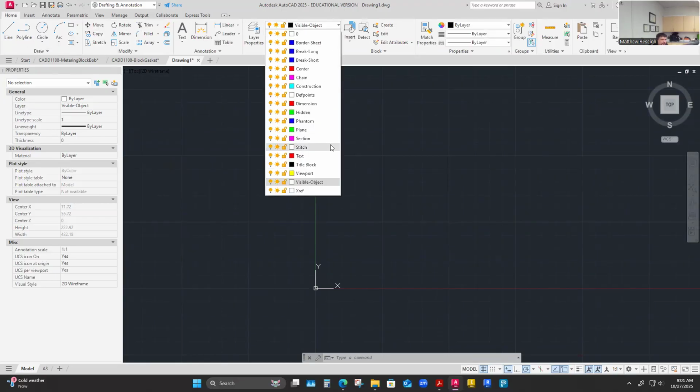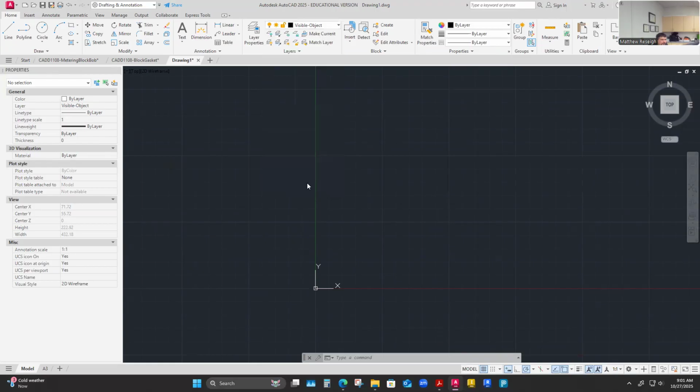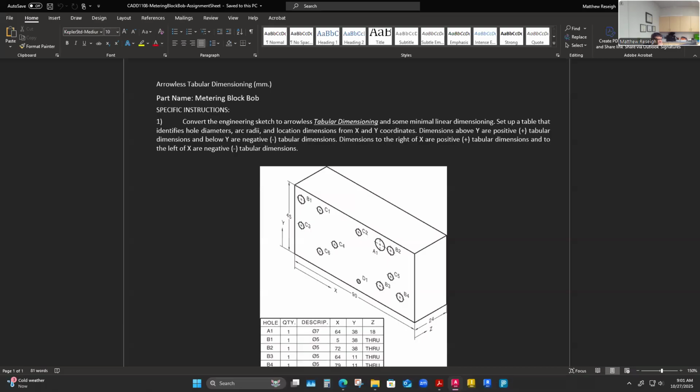There might not be too much construction work needed on this. I could probably almost just draw this straight from scratch. From 0, 0, remember, if you're going to draw from 0, 0, what you have control over here is it's spitting out the coordinate points of where that line is going to start. So I could just say 0, tab, 0, and it's going to move my cursor to 0, 0, right? So to me, this is the way I was going to draw. This is how tall? 45, 90, 24.